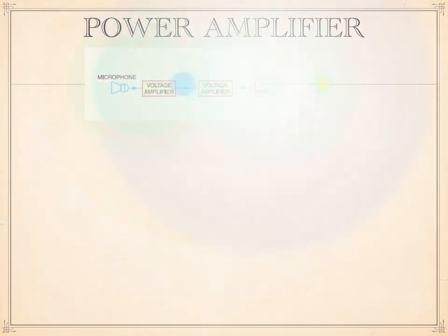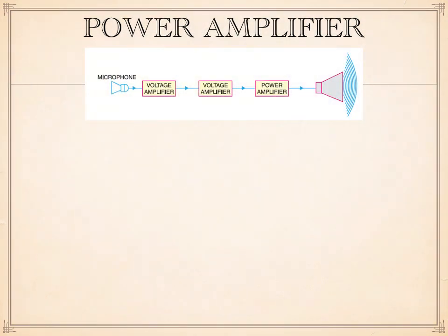Coming to the definition, power amplifiers give high output power. The figure shows a multi-stage audio amplifier in which microphone output is amplified and fed to the speakers. Multi-stage amplification is required to achieve high gain. In multi-stage amplifiers, initial and intermediate stages are small signal amplifiers or voltage amplifiers, whereas the final or the output stage drives devices like CRT, transducer, servo motor, or in this case a loudspeaker. So a power amplifier is used as the last stage of amplification.